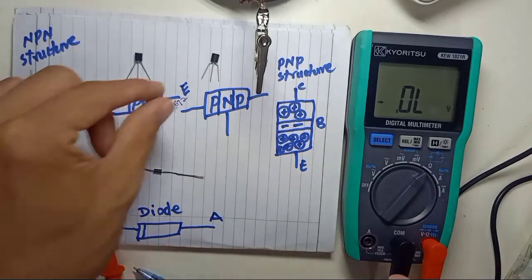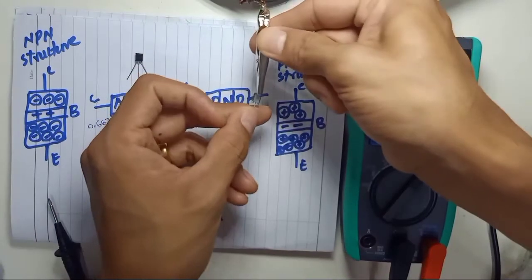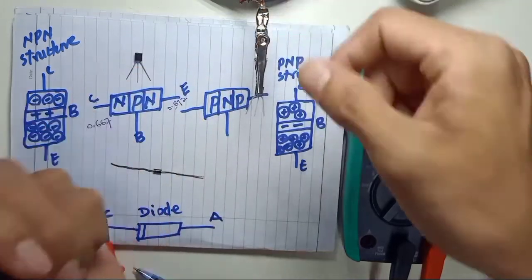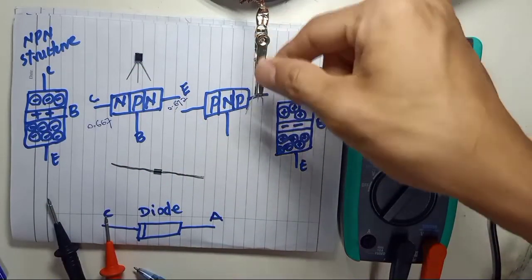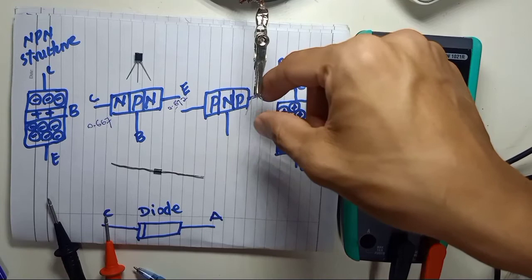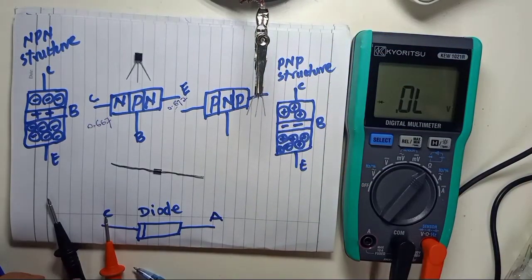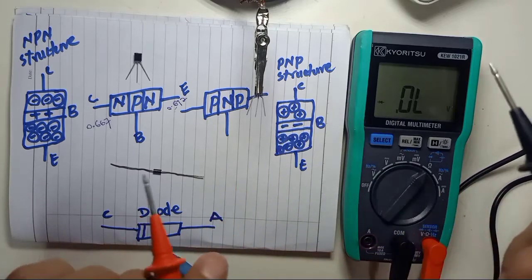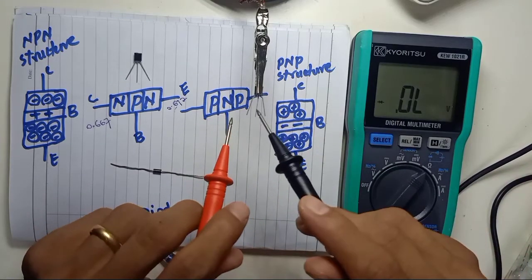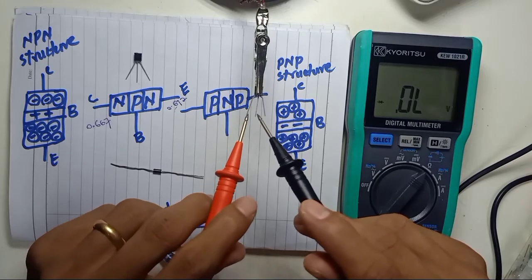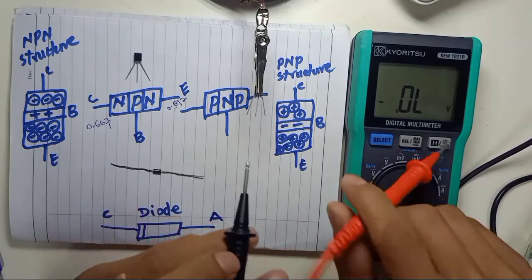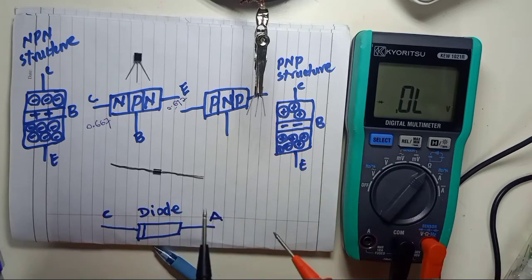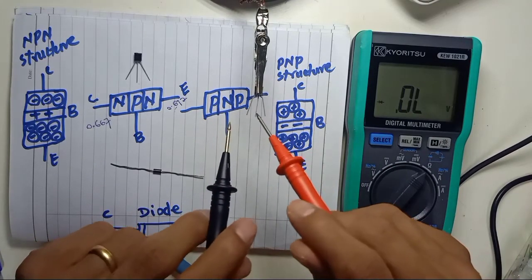Then another one. You take your transistor again. We didn't check which number this transistor is, but we just identify whether it is NPN or PNP, and which side is emitter and which is collector. Same as the first method, no matter which side you apply.